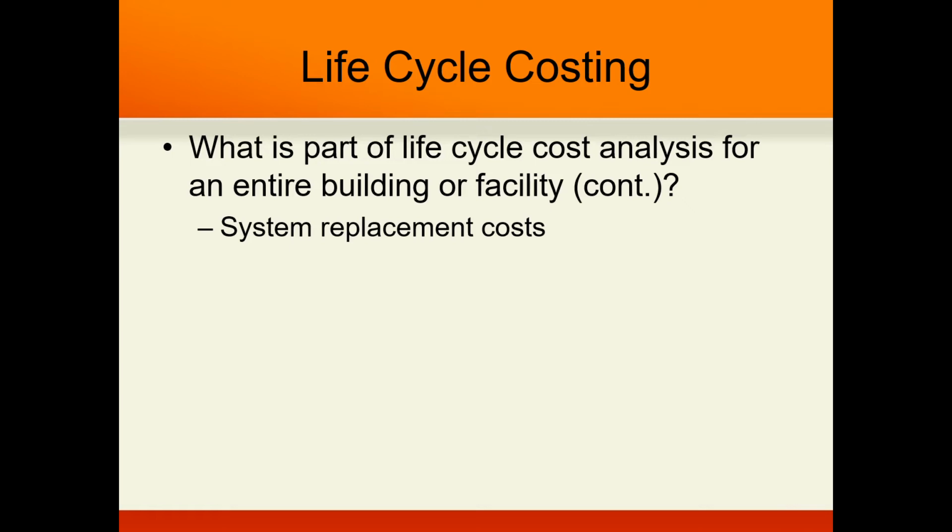So what else is included in that? System replacement costs. You know that you're going to replace your HVAC system about every 15 years. So if we look at about a 50-year life, we're going to be replacing that HVAC system at least twice from the initial. You want to make sure that that gets included in.